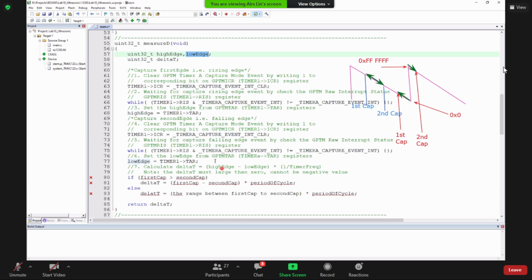Okay, so this is delta t. The result is in seconds. So this delta t, we cannot use unsigned. We have to use double. Change your measurement d to double. I will update my website. And here it is measure t, not d. So the measure t function returns the data type double, and then change this one, the delta t, to double.